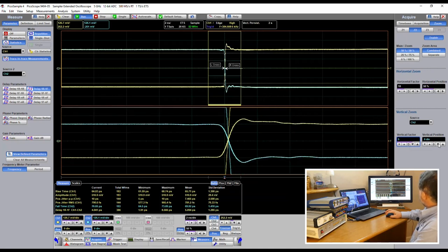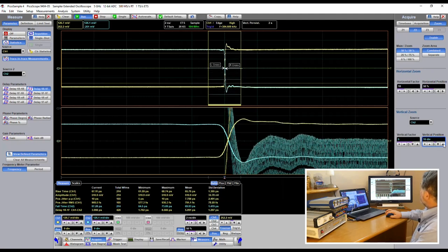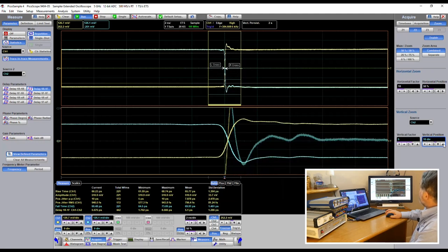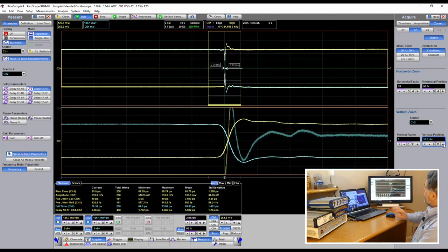And if I move that box down the screen, there we can see that second zoom window, revealing now all the waveform detail at the overshoot of that negative edge. And we can see there that we're beginning to really benefit now from 12-bit A to D resolution, and we're seeing all the detail still without any steppiness in that waveform there.